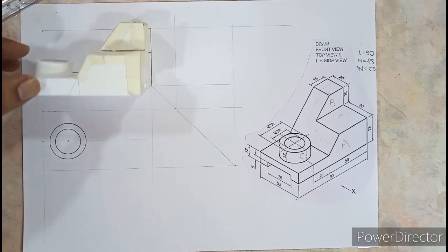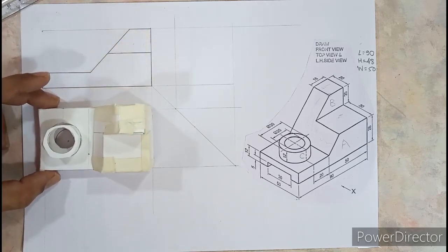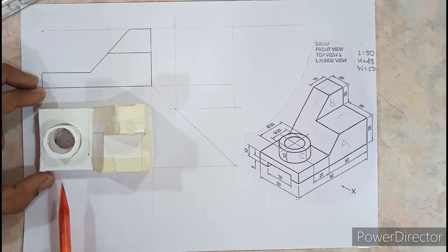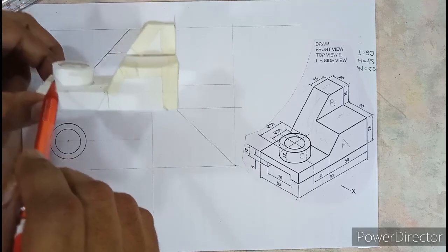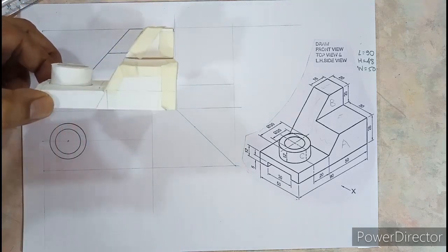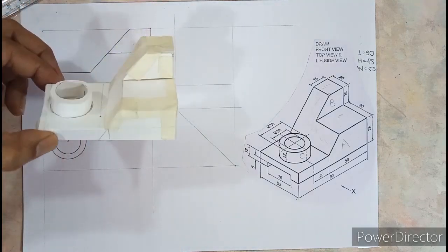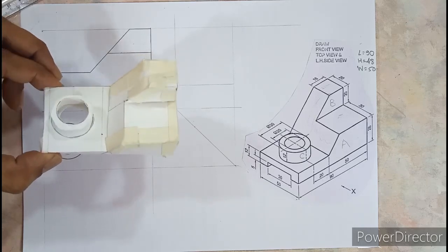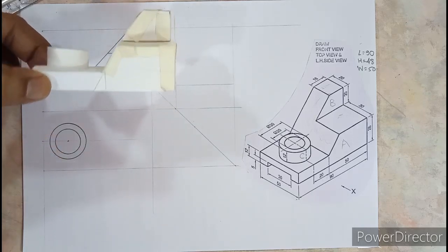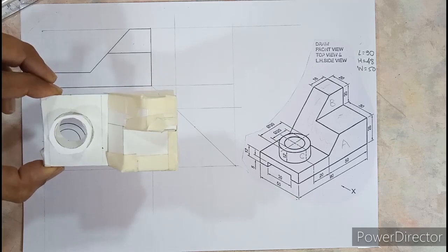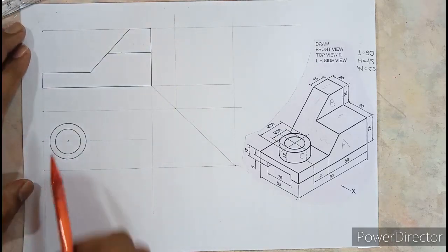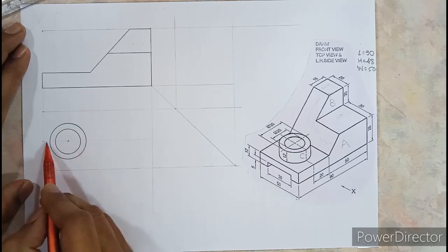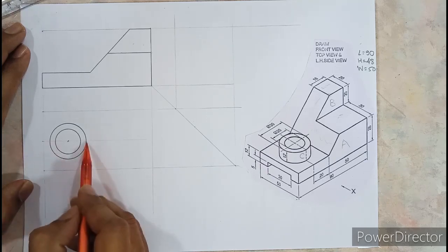And if you drop this down, this is the top view. So observation is from this side, that is what you have to visualize. And when you look at the cylinder, it will be seen as a rectangle. So this cylinder will be seen as a rectangle in the front view. In the top view, it will be seen as a circle. Front view, rectangle; top view, circle. Right now you are looking from this side, so you can see this part of the cylinder. You cannot see the other part.